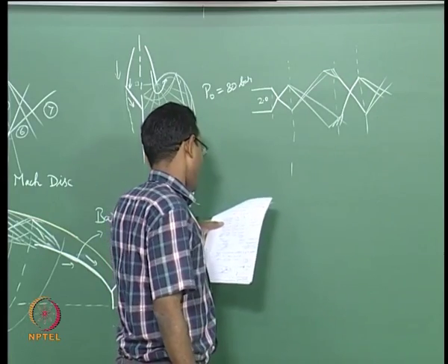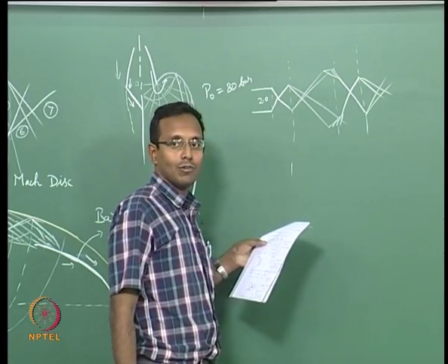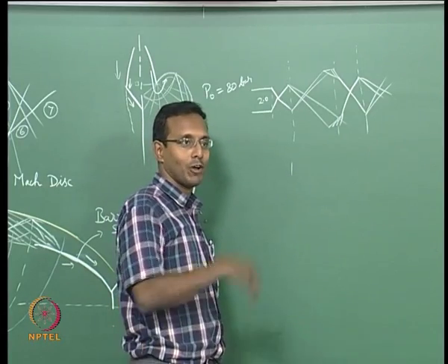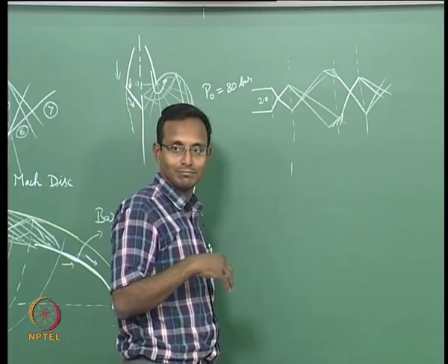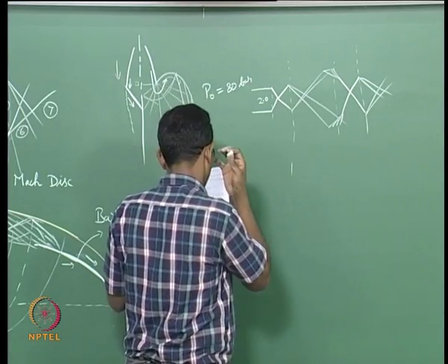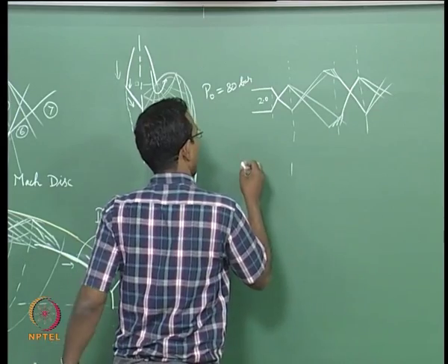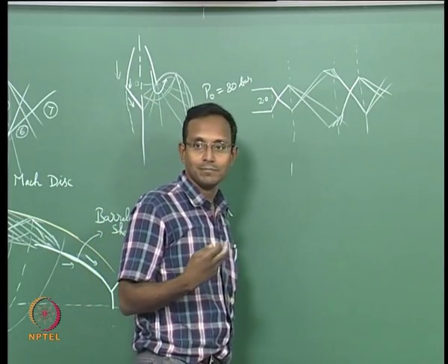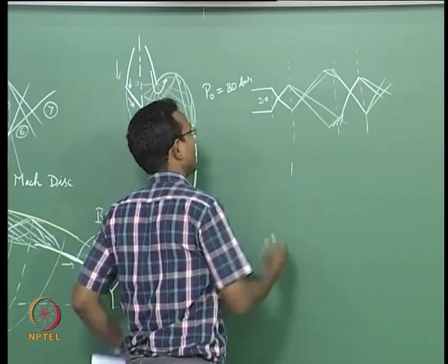So I want to find a pressure where it is over expanded, back pressure I want to decide. I am choosing my rocket to fly at different altitudes, I do not know what atmosphere it is, I am just going to pick some case. So I am going to say let us find a value below P critical 2 and above P critical 3.